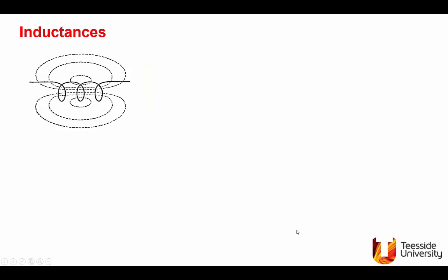We know now what reluctance is. Now we consider inductances. Inductances are associated with magnetic fields, and you would recall seeing them in equivalent circuits of electromechanical devices. Also, any of you who did power electronics would come across situations where we use an inductor, or even in filters and low signal electronics. Terms such as self, mutual, and leakage inductances are used, but what do they mean?